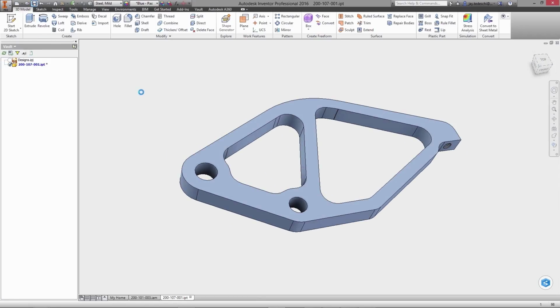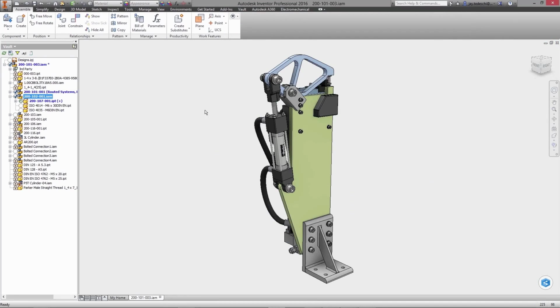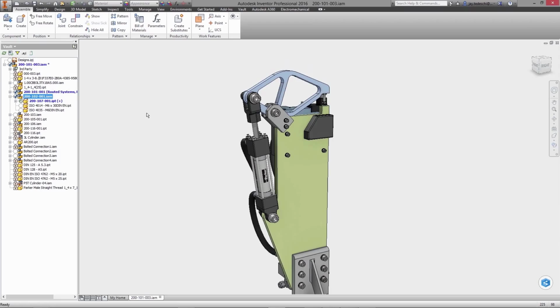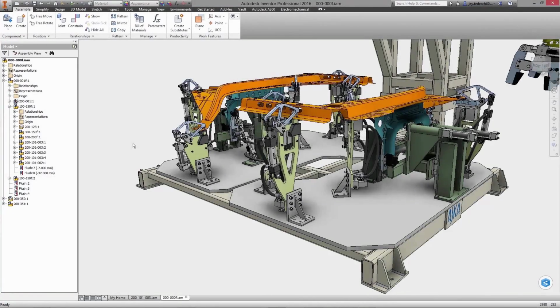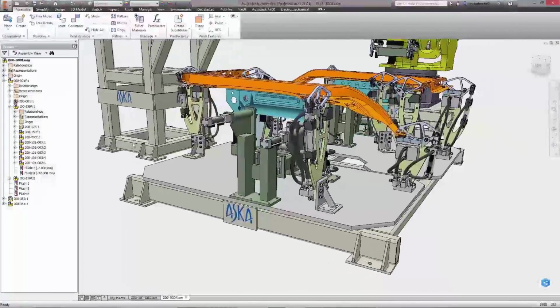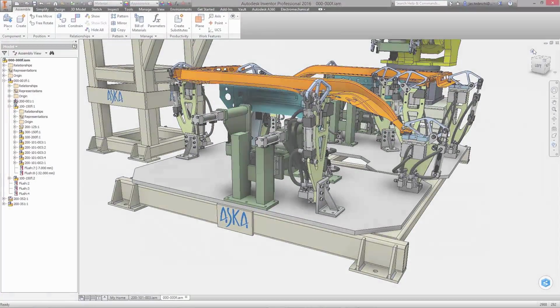The Shape Generator process was also used on the main clamp backplate, and here we used Inventor's Replace Component functionality to swap the new for the old. Finally, these changes are driven down to the assembly, and all existing instances are updated with the new configuration.